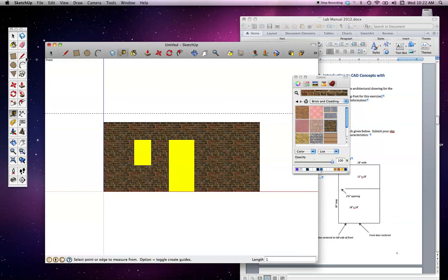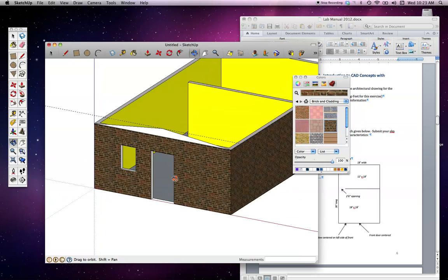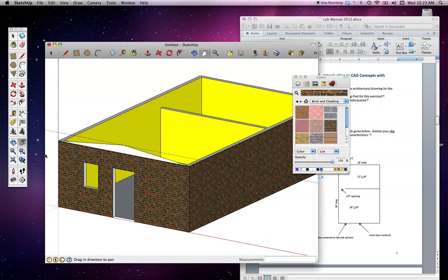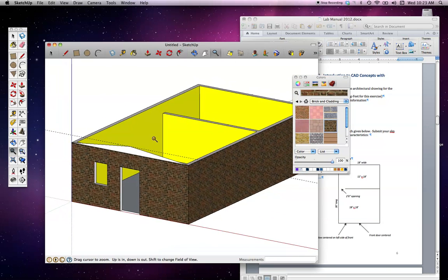And now I'm going to draw a line from this corner to the... now if I just rest over the midpoint for a minute, watch what happens. See, now it knows I want to be right at that distance. And I'm going to snap to this line, and then I'll snap and close over here. All right, now I'm orbiting this. I'll orbit this a little bit. You have to move around a little bit. Sometimes you have to maybe use the pan tool or zoom in or zoom out just a little bit.